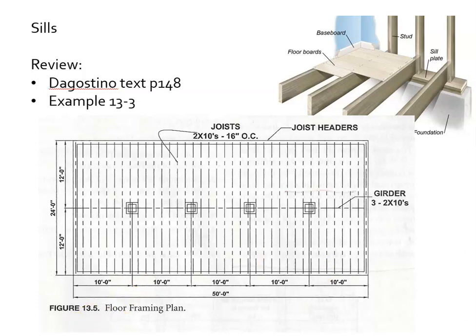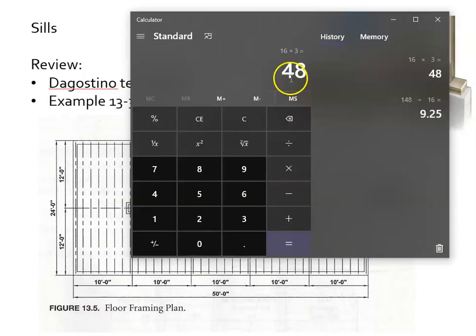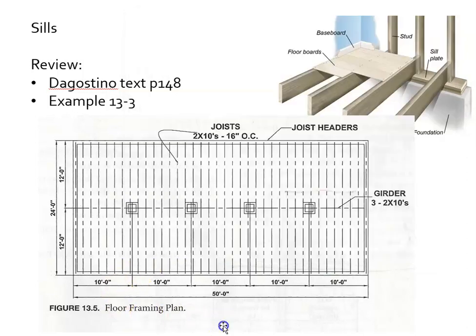Otherwise, if we bought 16-footers and we had 3 of them, that would take us 48 of these feet. Carpenters in the field would figure this out and probably not just add on a little 2-foot piece. They would do the math and come up with bigger, better pieces. You don't want to just add on tiny little 1 and 2-foot pieces when you get to the end.